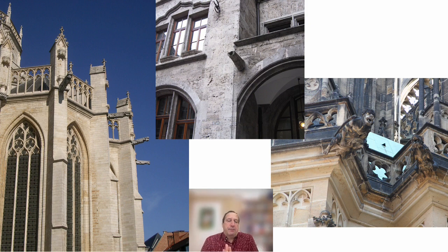Here, I'm going to go back to older buildings. A lot of times you'll go on tours and they'll talk about how these gargoyles were there to scare away the bad spirits, which is a good story. But really the majority of them are there exactly for rainwater shedding. They are the way that they hid rainwater leaders and downspouts and made them durable. You can even see there's a copper pipe being used to make the tongue of that gargoyle.